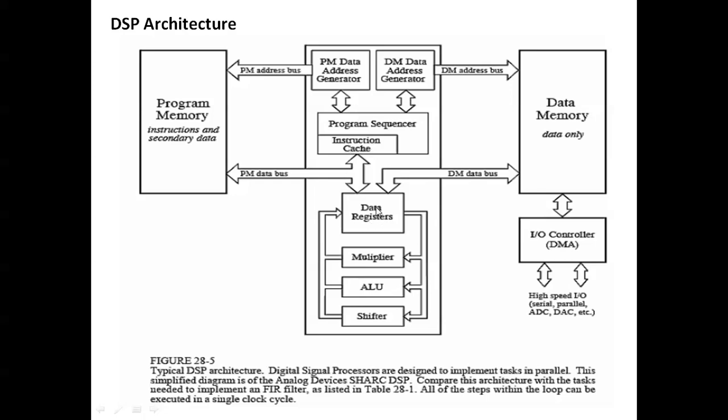So what is a register? A register is storing the data. You know that a flip flop and a latch are one bit registers. A combination or integration of more than one flip flop is a register. So the register might be 4 bit, 8 bit, depending upon the size of the register. Here they have the data register. So that register will store the data or instruction or whatever temporary data and everything. So that is a data register. That means it will store the data.